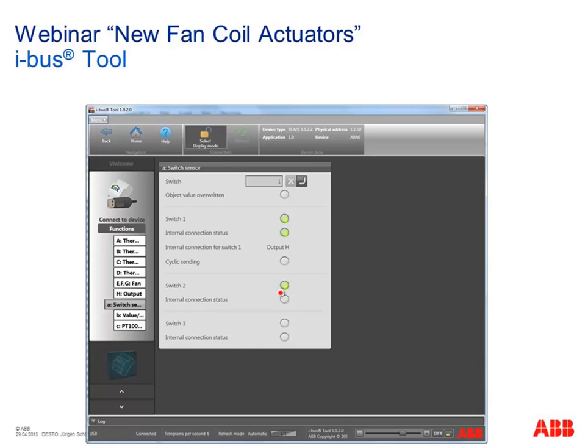Additionally, I have also enabled the communication object for switching 2, but here, okay, no internal communication. The same principle here, click on this field and enter the value, for example 0, and then we can simulate, for example, the opening of our input, like we open now our standard push button. Press here on the button, and then we override the existing value.